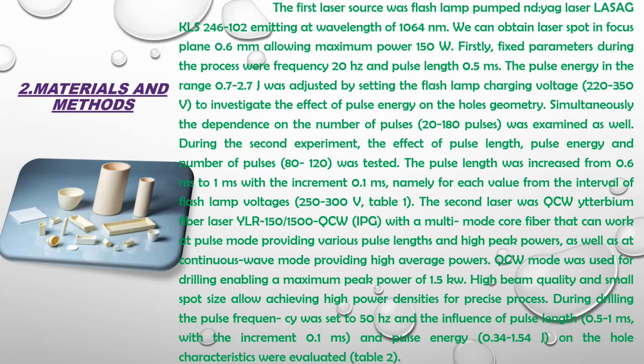During drilling, the pulse frequency was set to 50 Hz, and the influence of pulse length with the increment of the pulse energy on the hole characteristics were evaluated.